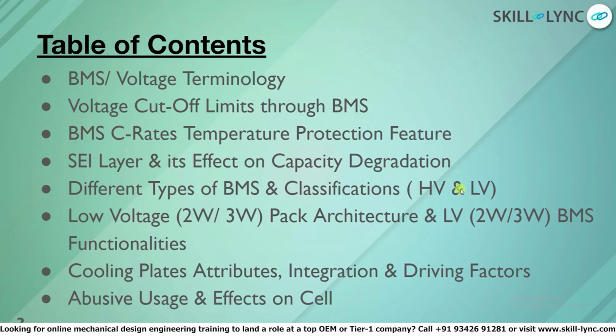What are the different types of BMSs, and how are they classified into high voltage and low voltage applications, and then we'll also check what the low voltage pack architectures are along with high voltage architectures. Also we would discuss what their functionalities are mainly for high voltage and low voltage, what the main differences between them are, and then we'll touch base again on the cooling plate attributes, how they are integrated, and what the driving factors for the cooling plate are. Then we'll also see what the abusive usage conditions are, their effect on the cell, and how BMS overall, at the end you will have an understanding of how BMS will protect the cell from all those abusive usage conditions.